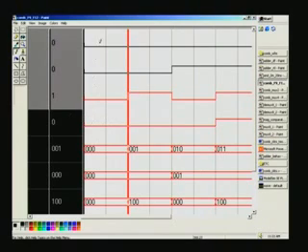For example, here, this is 000, and then 001, right? And here 100. So all this should necessarily produce only 0, because the maximum number of 1s is only 1, right? And beyond this, here you have 0, then 1, 1. So two 1s are encountered, so it goes high. That's what majority logic is.